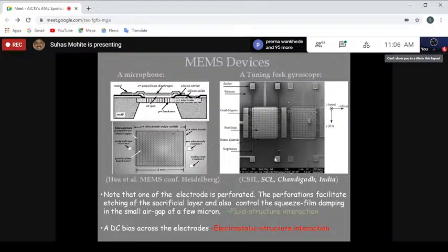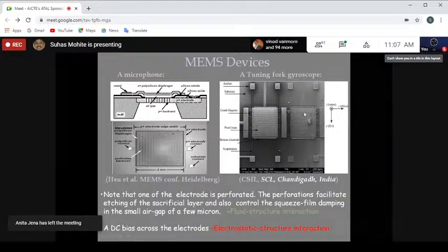No, not to reduce the weight. Heat transfer, sir? No, because this is not a heat device, this is a dynamical, structural device, not having anything to do with weight or even heat transfer. But the manufacturing process or fabrication process you have to think about. This is a suspended structure, remember. And the two processes that are used are deposition and removing unwanted material underneath the structure, etching.